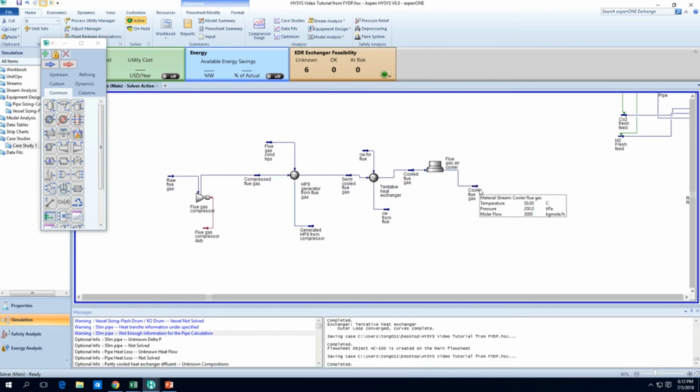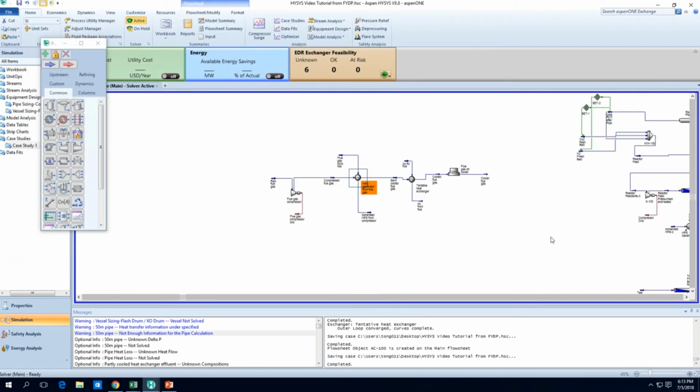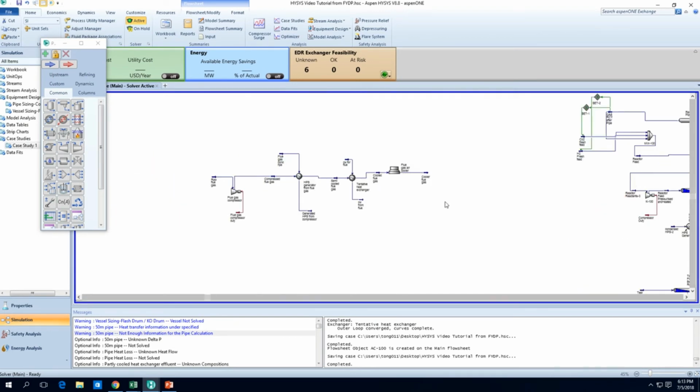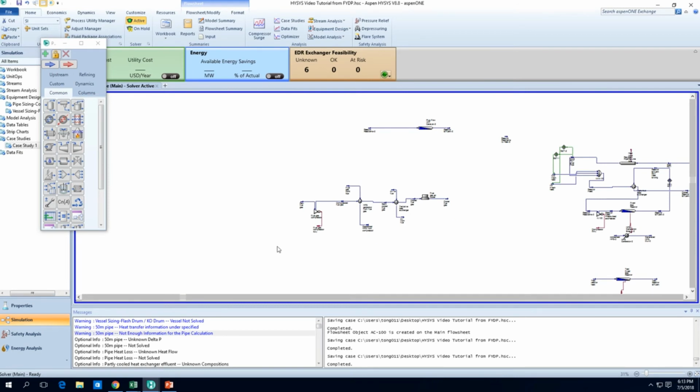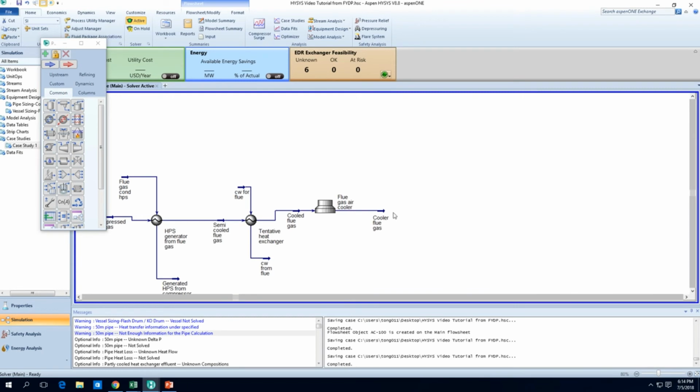Okay, so that's part 1. We have it at about 200 kPa. And we probably want to have a bit more. So we need a bit more pressure, perhaps. But maybe we'll do that later. Okay, so that's just preparing the flue gas at the correct temperature at pressure. So this is a 2-bar cooled flue gas, and the first step is probably we want to do washing out using water.